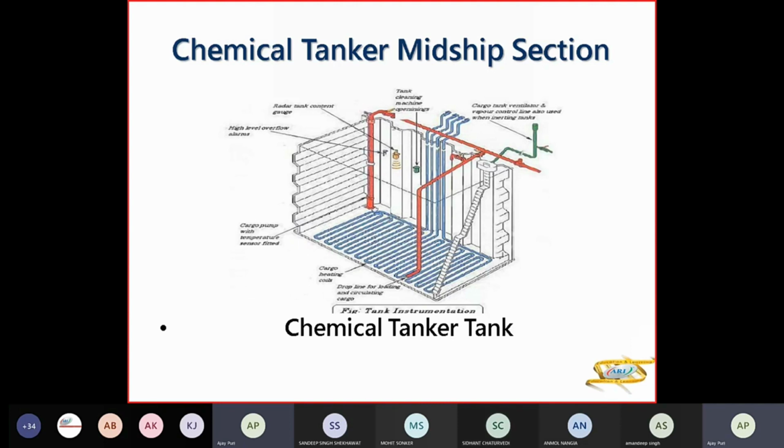But it is common to the entire ship. On a tanker there is only one PV breaker. PV valves will be on every tank or every line, but the PV breaker will be in only one place, because your cargo is homogeneous, so intermixing of cargo is not a problem. But in chemical tankers, you have 4,500 to 5,000 grades of cargo. Any cargo might not be compatible with any other cargo. So in case you have a PV breaker, contamination can occur on the chemical tanker. That is why the gases are kept separate. Every tank will have a separate set of PV valves, not on a common line. Every tank will have a Framo pump. Every tank will have a separate line. Everything will be separate. Nothing combined.